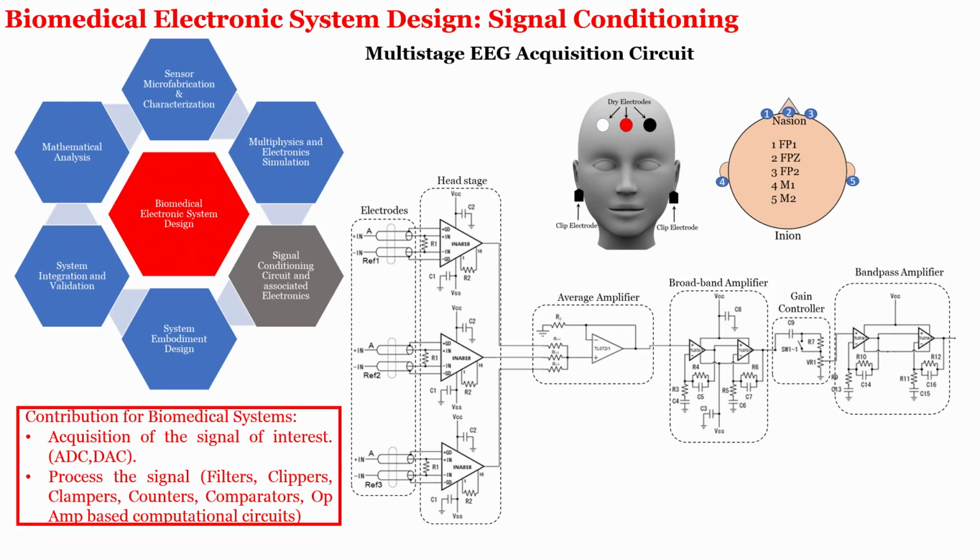Now, there is one more called ECoG that we may not have discussed in this particular topic, but ECoG stands for electrocorticography, that is a signal from the brain. This EEG is a little bit different from ECoG because EEG is from the scalp electrodes. From the scalp there is an impedance that is provided by the skull, and that is why the EEG signals are a little bit different from the ECoG signals. However, both originate from the brain.